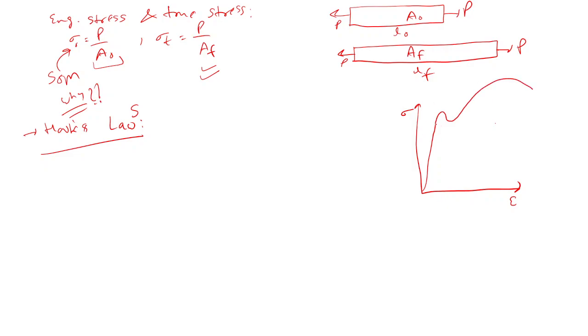Actually, let's suppose this is the proportional limit, and after this it changes. But when Hooke's law was defined, it was said that till the elastic limit, stress is proportional to strain. But actually it is till the proportional limit, right? So ideally, theoretically, Hooke's law is till the elastic limit, but practically it is till the proportional limit. That is the difference we can think of.